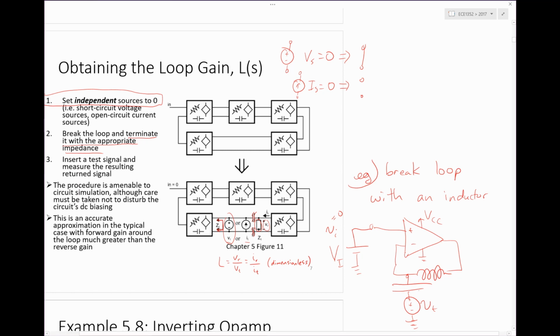And you make those values large enough so that you can even inject a 1 kilohertz test signal. You can even inject a 10 hertz test signal, or whatever is the lowest you need to go, and the capacitor still looks like a short. And it's a common mistake that I've seen a couple of students make every year.